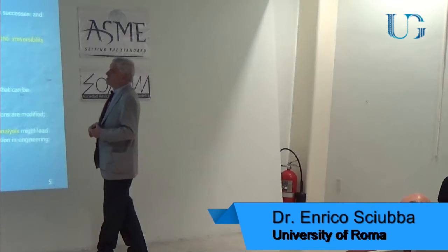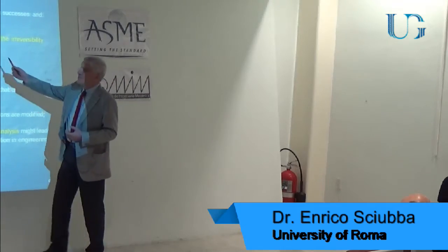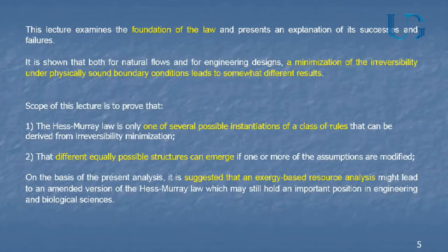I will show that both for natural and engineering designs, a minimization of the irreversibility, the entropy production, under realistic boundary conditions leads to different results than the Hess-Murray law. I will also try to show that the Hess-Murray law is only one of a number of possible laws that can apply to bifurcated flows.